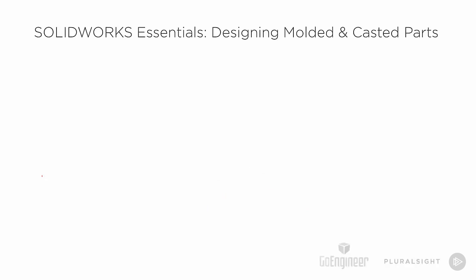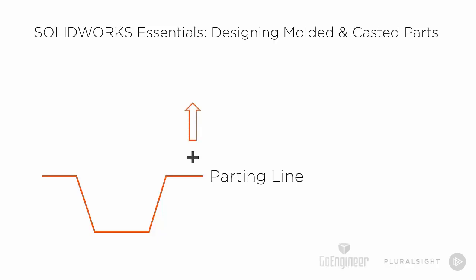So I want to take a few moments and illustrate what I mean by draft. So I'll just come in here and draw a pretty basic shape. And from here, we're going to let this represent our parting line. It's a term used a lot when we're talking about molds. And this has to do with the place where the mold splits into positive and negative directions. Negative is not a bad term. It just means that it's opposite of the positive direction.